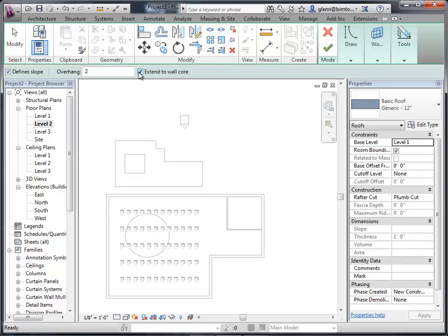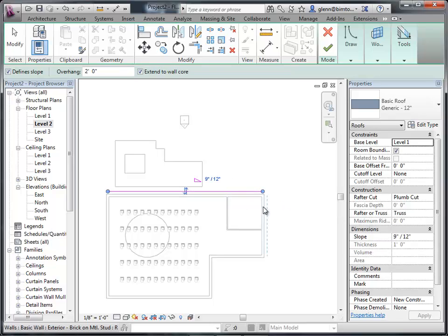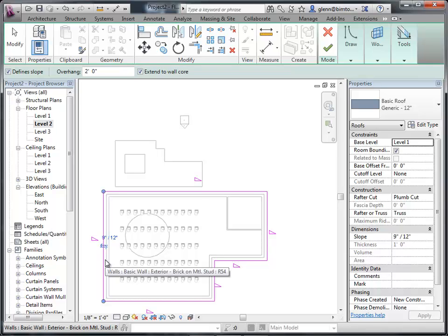What we'll do now is just go ahead and pick some walls. These are all these little 2-foot overhangs. So even though I'm picking the wall, notice how it hangs out a little bit. That's looking pretty good. I've got a nice continuous boundary. If somehow your walls didn't line up in such a way that you have a nice continuous boundary, we're going to go ahead and do a little training, because again, you need a nice continuous boundary, same as the rules for the floor.